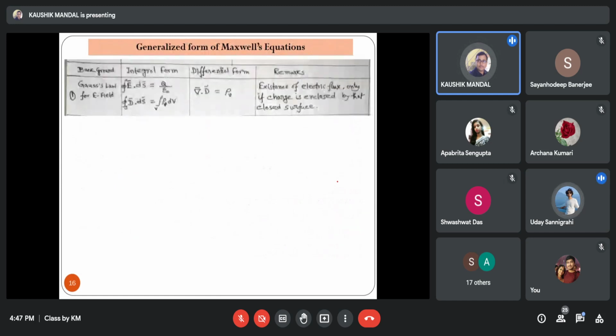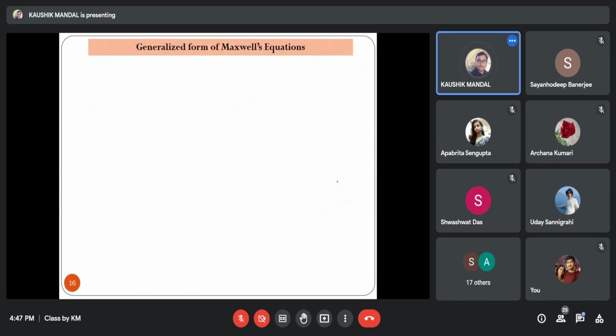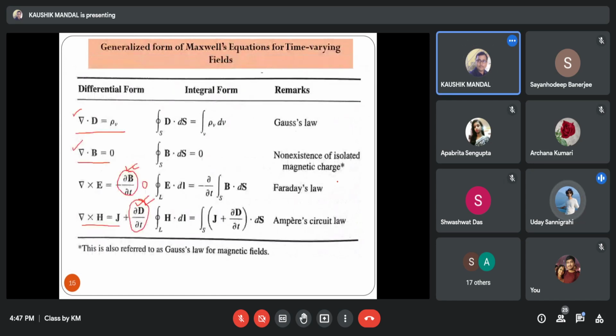Now I have summarized. Displacement current also depends on the electric medium. Yes, that's also true. In that equation, JD equal to del D del T, and D equal to epsilon E, where epsilon is the permittivity. So it also depends on the dielectric medium.